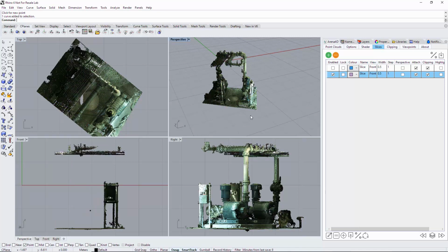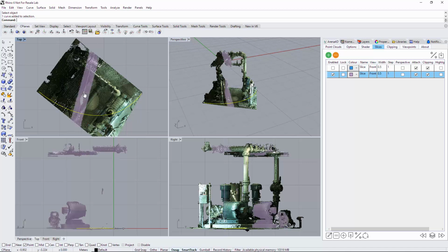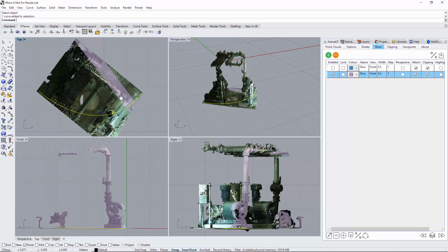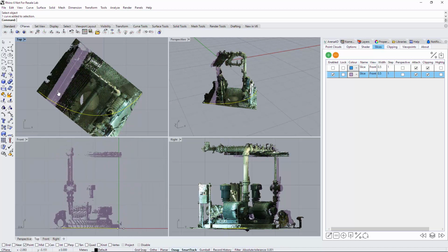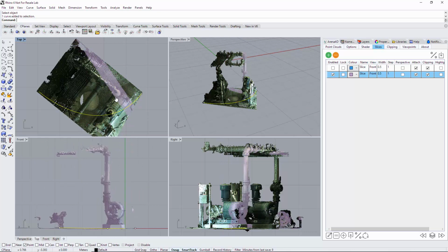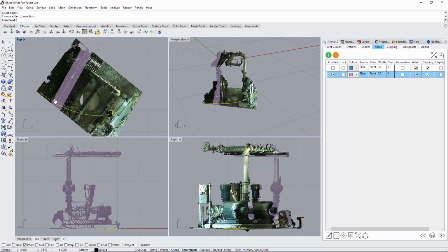and unselect the line we have. So the curve I've created, unselect that, click align to curve, correct slice is selected, align to curve, and then select the line we drew. So there it is there. Now if I drag this slice, you can see it slices along that curve. Very, very useful if your point cloud goes around corners, etc. Very, very neat way of doing it.